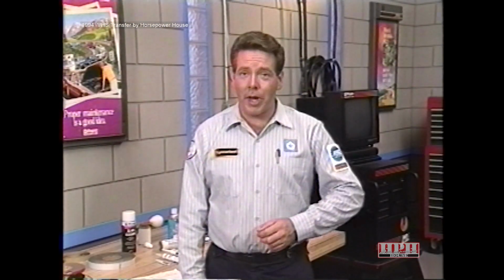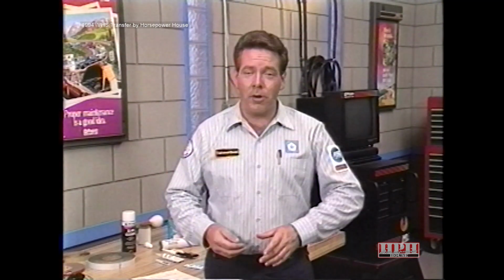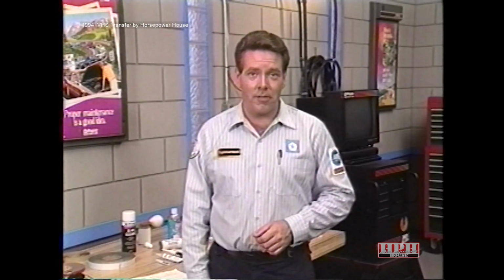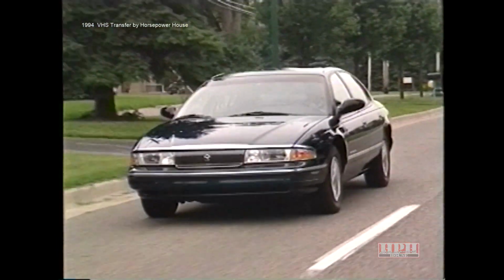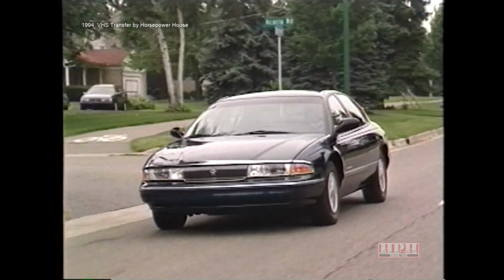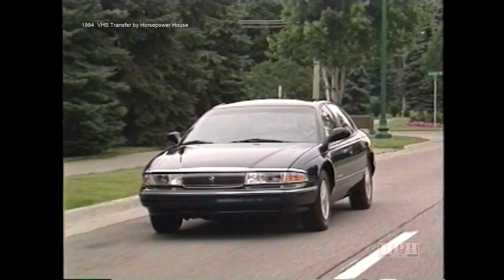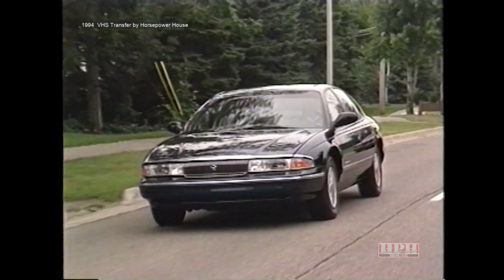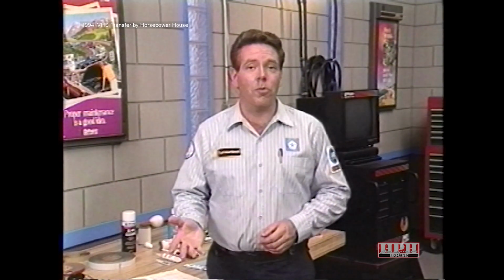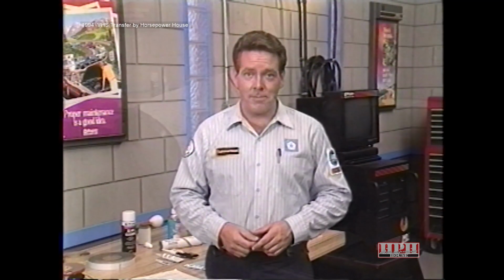Before we conclude the diagnostic portion of the program, there is still one more very important diagnostic test to discuss: the road test. Conducted on a quiet, relatively straight street where you can duplicate the problem-causing conditions, the road test could be your most effective diagnostic tool for wind noise detection. And it may also be helpful in locating water leaks. But before you jump in the car, here are some things to keep in mind.